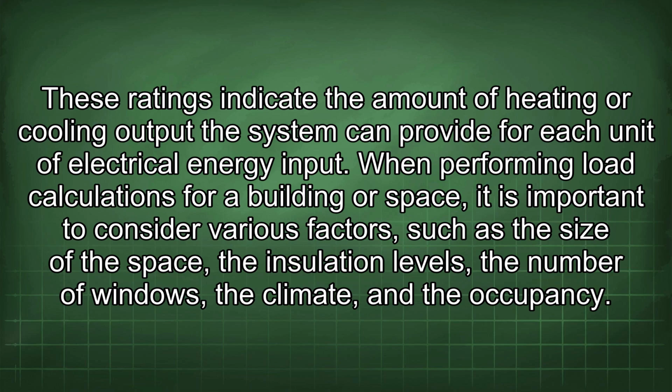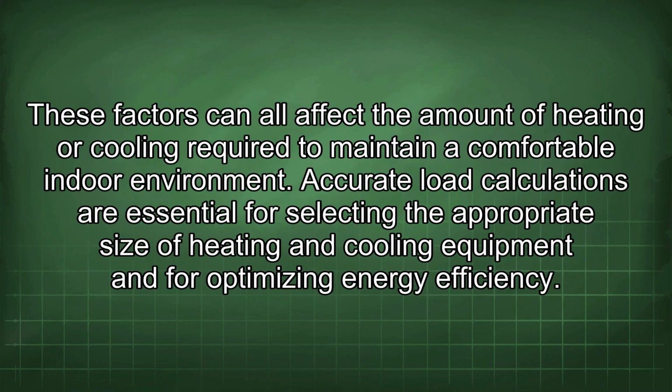When performing load calculations for a building or space, it is important to consider various factors, such as the size of the space, the insulation levels, the number of windows, the climate, and the occupancy. These factors can all affect the amount of heating or cooling required to maintain a comfortable indoor environment. Accurate load calculations are essential for selecting the appropriate size of heating and cooling equipment and for optimizing energy efficiency.